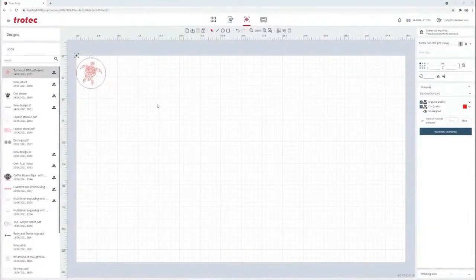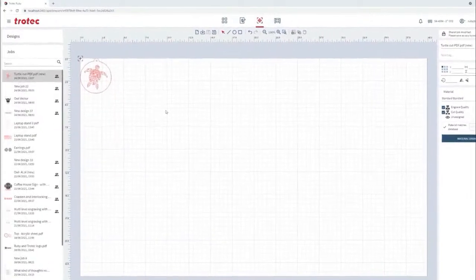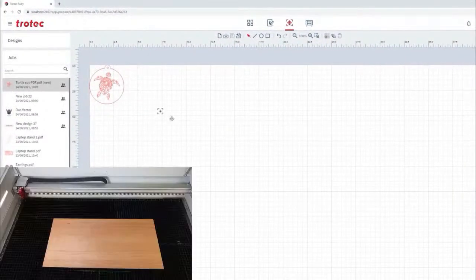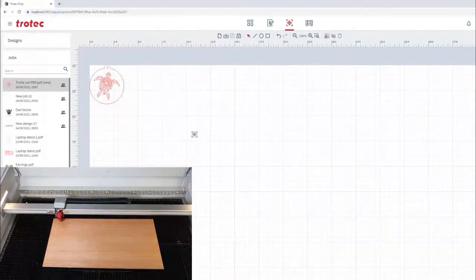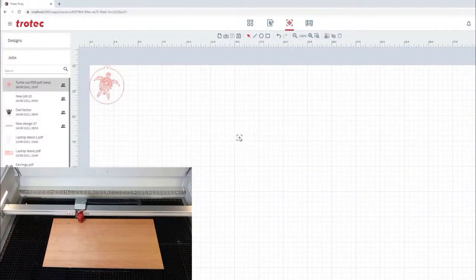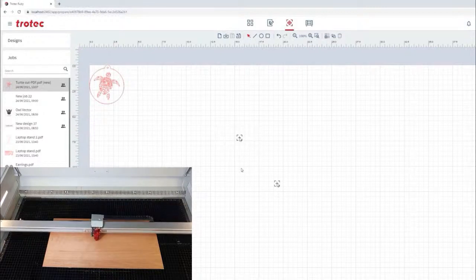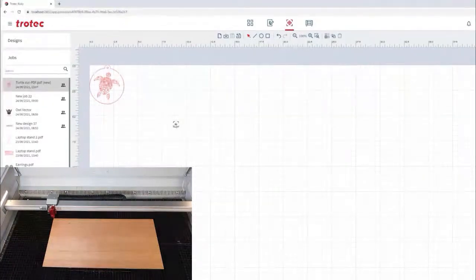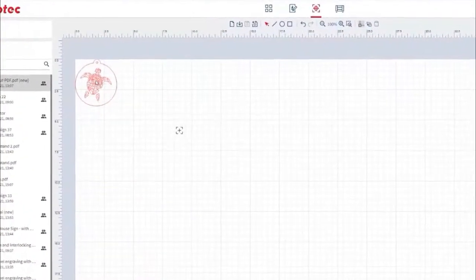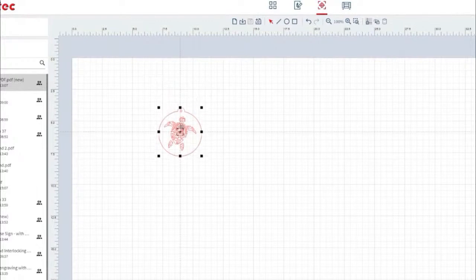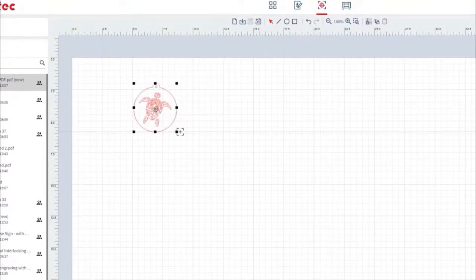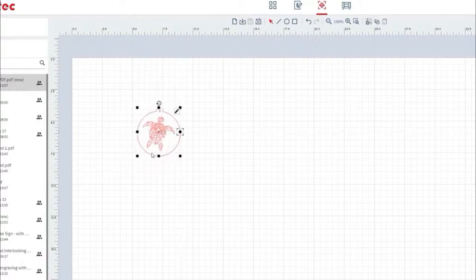Within the prepare screen, the cursor can be selected and dragged to the location you want the file. This can also be accomplished with the arrow keys on board the laser system, showing the laser orientation with the red dot pointer. Once the laser head has been selected, the file can be snapped to the crosshairs on the screen that matches the location of the laser head or material. The file can then snap to the center, bottom right, top left, bottom left, center right, as needed.